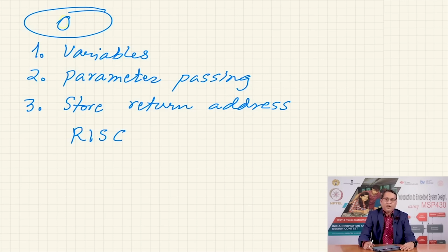Of course, if your application is so large that you cannot do with the number of registers available, clearly this is not an appropriate microcontroller for this application. You must find a microcontroller which has a suitable amount of SRAM available. But for very small applications, it is possible that you may get away without using any RAM. It still poses the question, how do you store the return address?